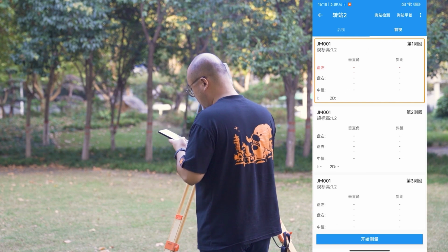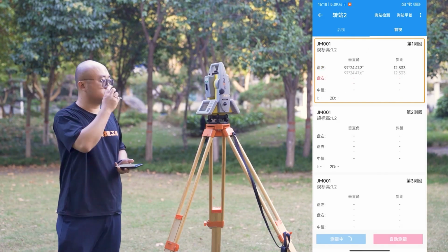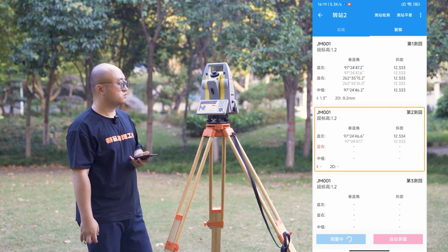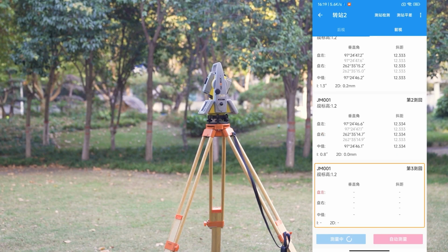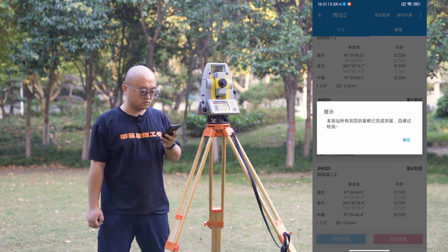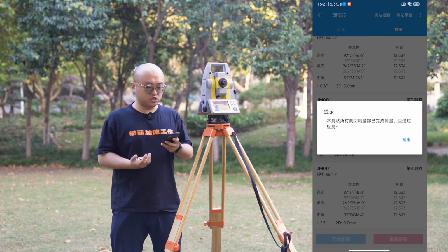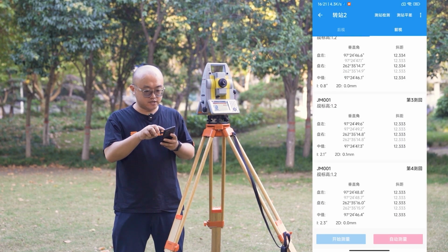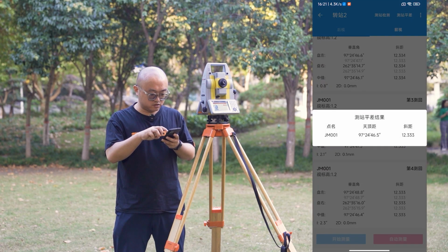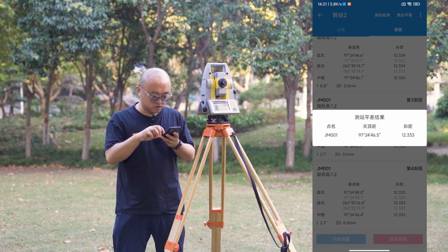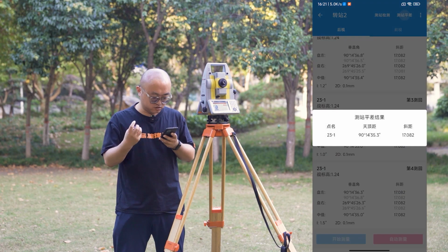Start measuring the first target. The current measurement loop has been completed. Start measuring the second measurement loop, the second target. Then the third measurement loop, the third target. Then the fourth measurement loop, the fourth target. All measurements have been completed. Okay, all the measurements of the backward and forward views have been completed. After the observation is completed, click on the station adjustment again to determine a result of 12.33 after the front view has been reduced. Then, look at the front view 17.082 again, and it is considered that the observation is complete.